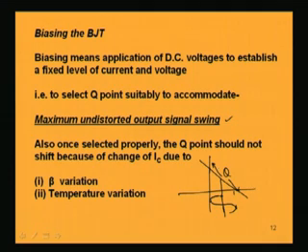the collector current IC is changed, then if it becomes higher, it will be shifting to the top, and that happens because of two reasons. One is change of beta value. Suppose during operation of the amplifier, we are changing the transistor, because of various reasons it may so happen that you have to change the transistor. And if we change the transistor, this beta value will not be the same,